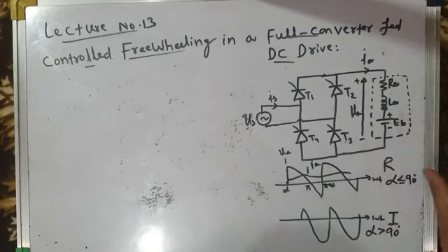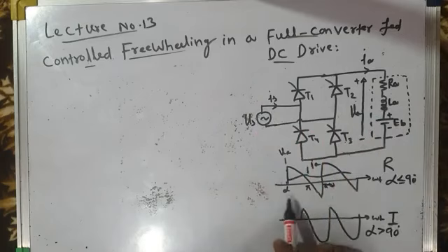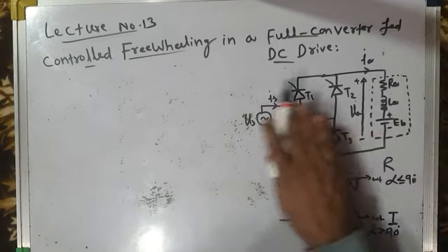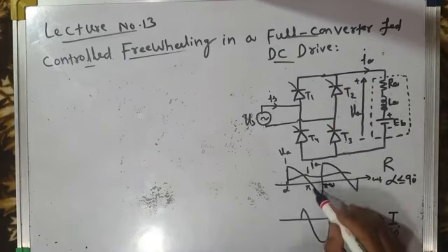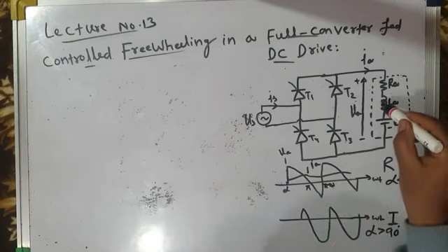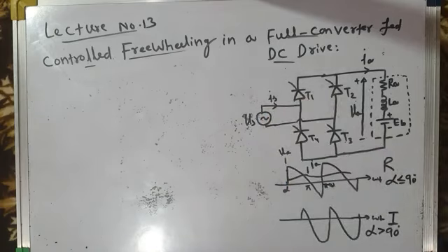I'm not talking of mechanical energy or I square R loss energy. A small amount of energy flows from source to inductance, and it is stored there. And during the negative segment of the load voltage, pi to pi plus alpha, this energy which was stored in the inductor is released and sent back to the source.